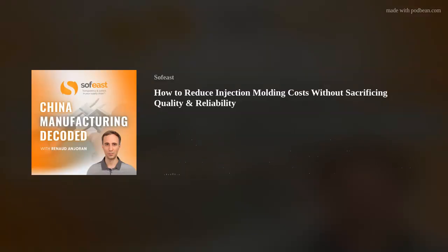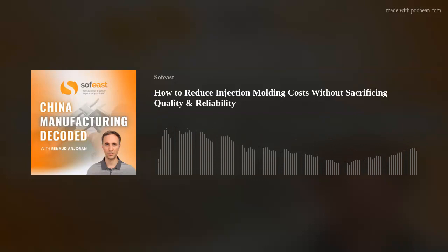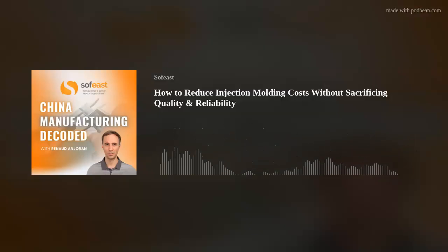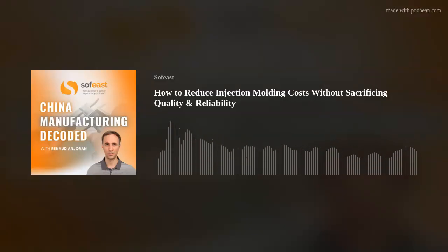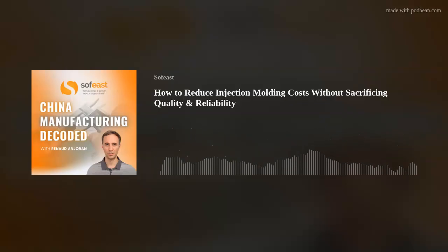Well, it depends. It's on the life expectancy of the product, how mature your market is, how mature your business is, how mature your product is. If this is your first rodeo and you've never sold anything before in your life, but you've just come up with this fantastic idea, let's go for it, then I would suggest that you go with the softer tool. You're still going to get 300,000 to 500,000 shots from that, which is a big number.